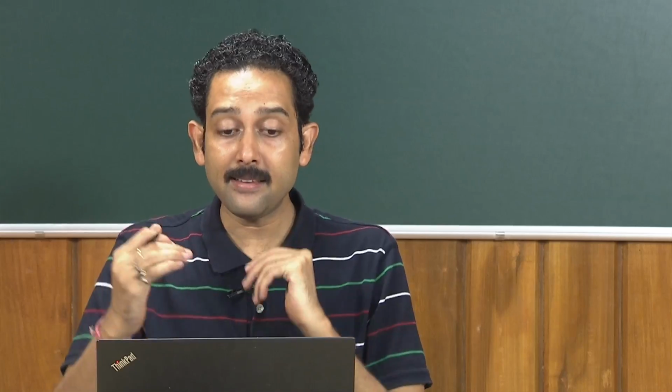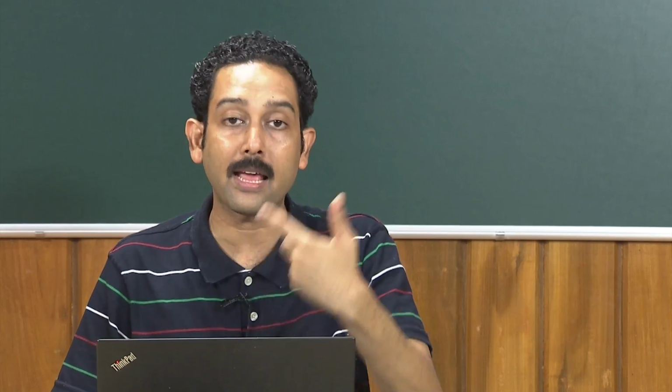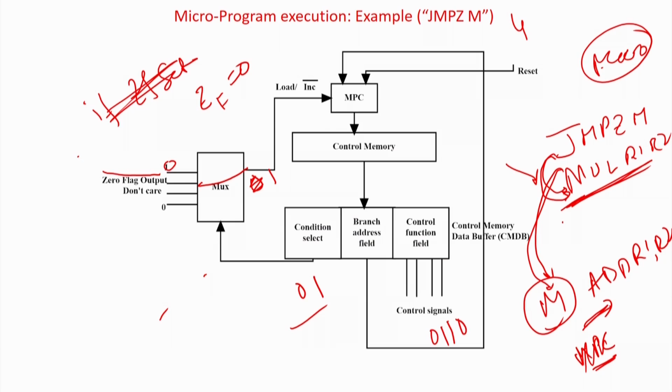But in fact this actually shows you how a total routine executes for a given macro instruction like jump, and also we have explicitly shown that there can also be jumps if you have a single microroutine for similar types of instructions. Like here we had a single routine for jump on 0 and jump on carry.